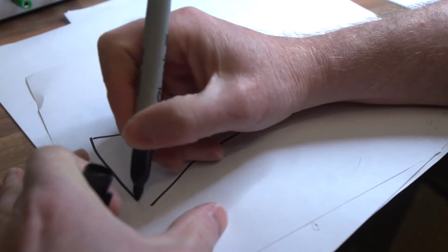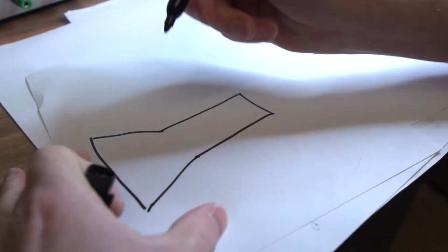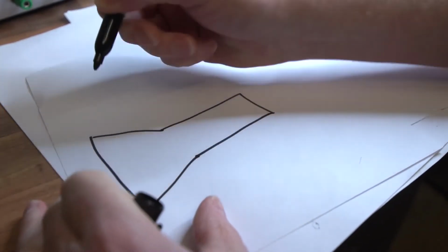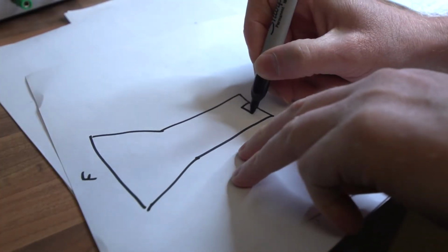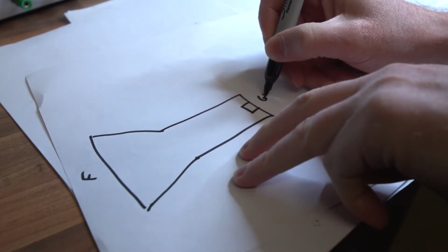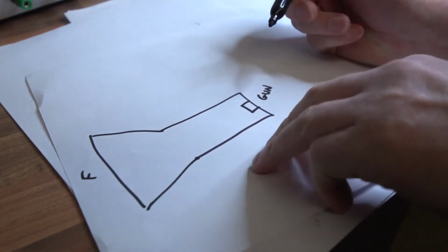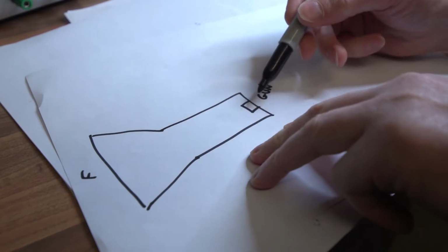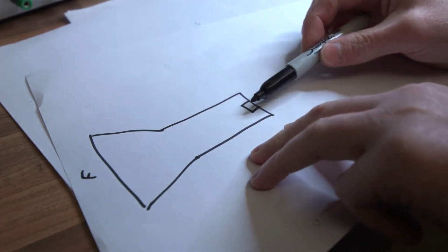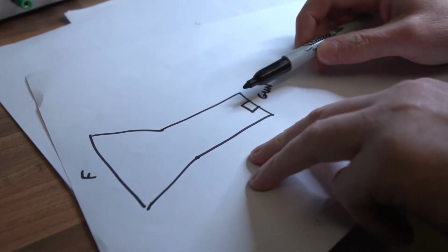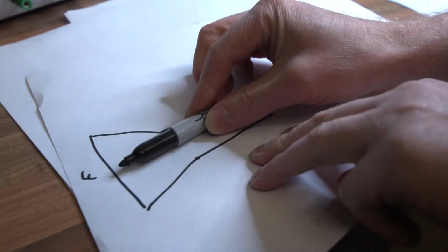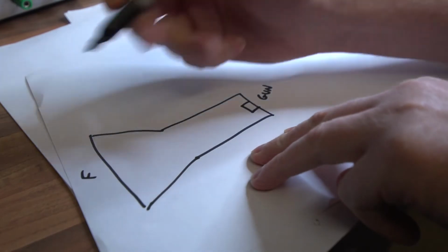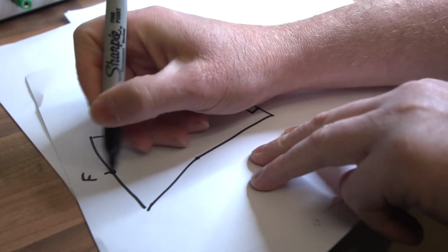like that. Imagine you're looking through the side of it there, and that's the front. Now, in the back of the tube you have an electron gun, which I'll just call gun. I'm simplifying this. From the gun, it generates a stream of negatively charged electrons, which fire. If you didn't do anything with the beam, it would fire out straight to the screen at the front, and you would end up with a dot just there.